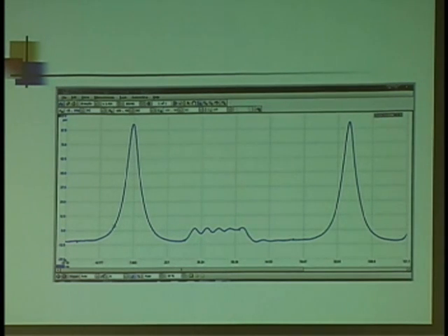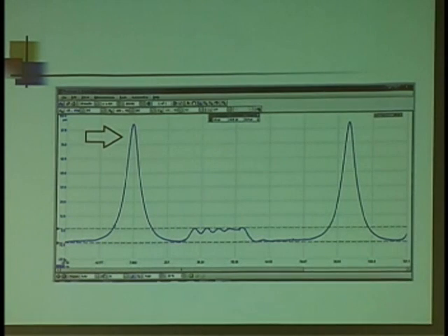Now the WPS comes with special hoses to use. If you use a PV350 or you adapt another sensor and you're using your traditional compression gauge, just like we did the old mechanical running compression, you've got to take the Schrader out so you don't get a peak. We're going to start off first. What are we referenced to? Atmospheric pressure. We're coming up on top dead center of the compression stroke. Again, this is a running engine, so I'm going to expect that number to be lower than what the cranking compression test was.